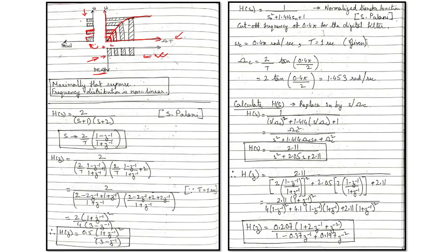However, as we go towards the higher frequency components, if you see in the digital domain, the frequency range has been compressed, even though we have not compressed the analog frequency while sampling in the analog domain. So you can see that there is a marked problem over here. There is a frequency compression at the high frequency levels.